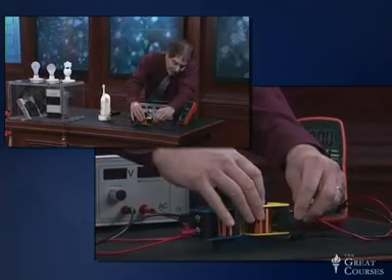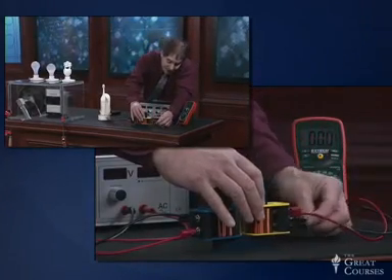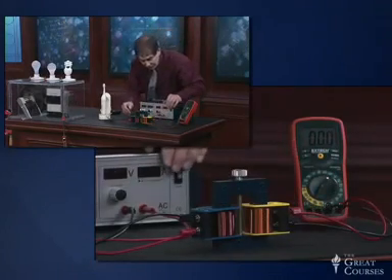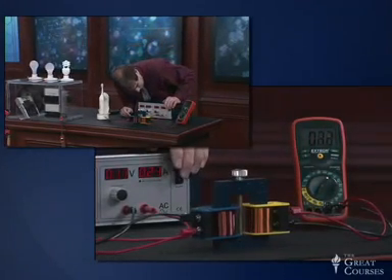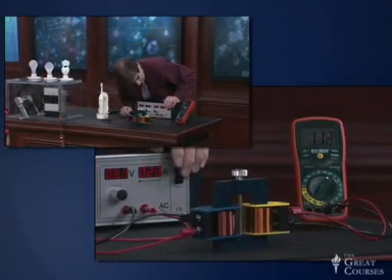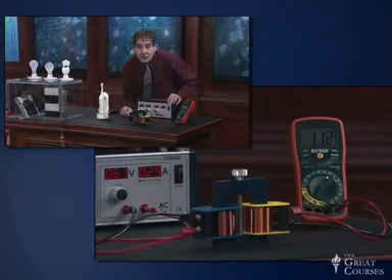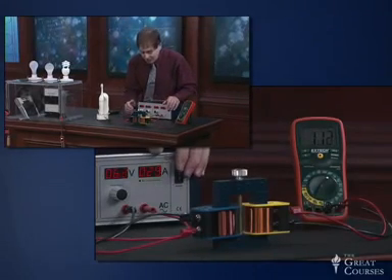This does not buy us more energy because we get less current out of it, and the product of current and voltage is electric power. So I'll turn this one on. I've got now about 6 volts again, and I've got 11 or so volts there. So now I've got a step-up transformer.